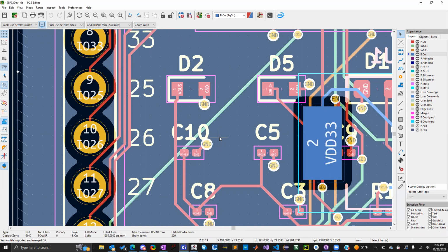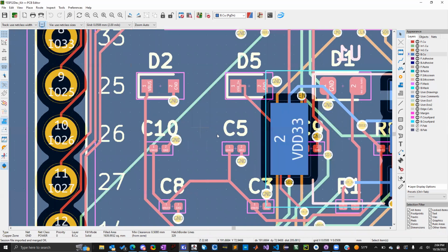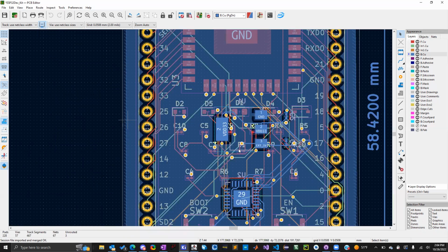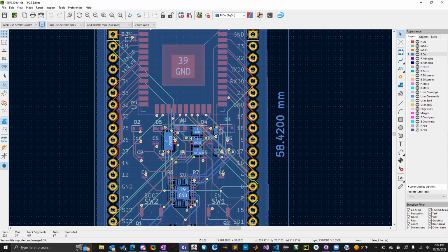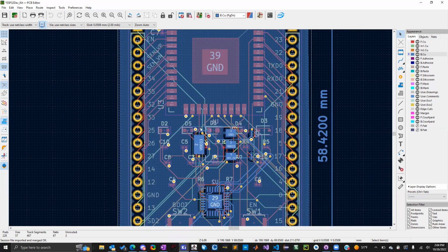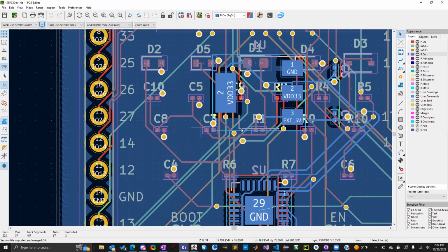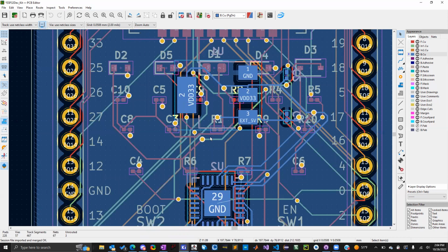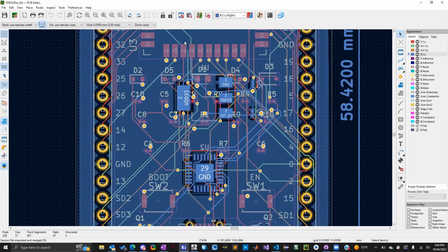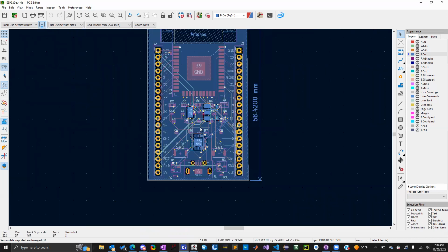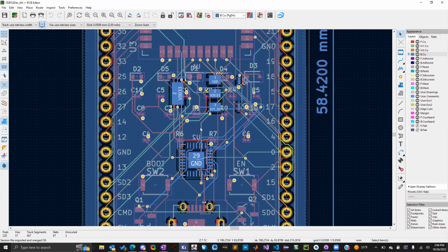through the auto router. The auto router is a lot like KiCad in that I can actually take this into the auto router and I can edit it as well. Really quick, I can edit like the tracks and the zones and stuff. I can add that in the auto router. I prefer to do everything in KiCad, so I would go back and forth. You can also make specific connections, but I wanted to leave this auto routed actually just so you guys could see this is what it comes up with.